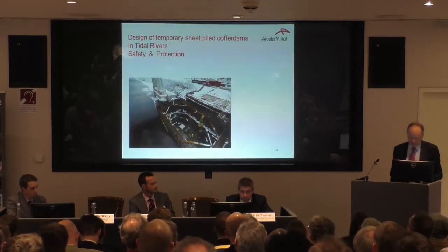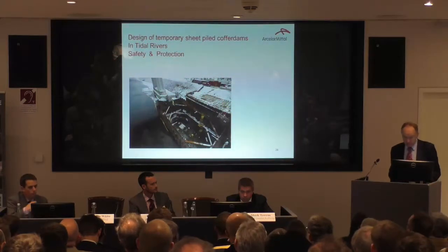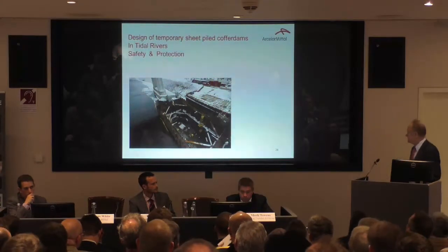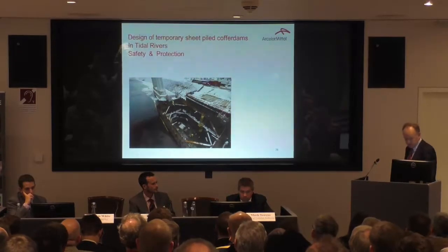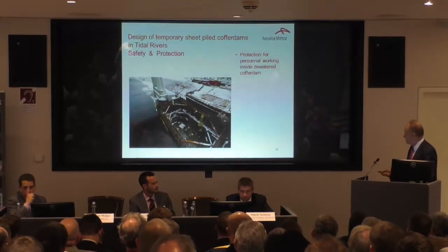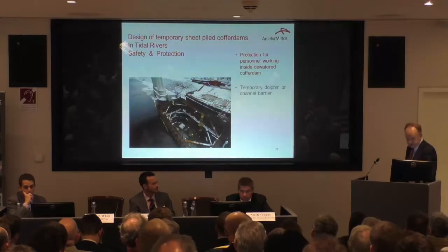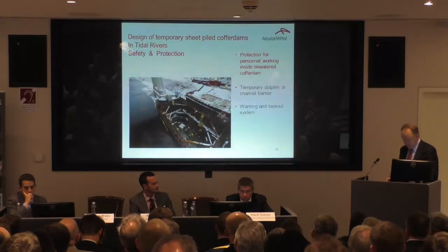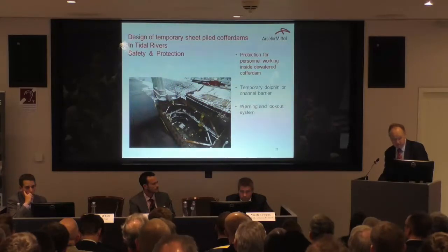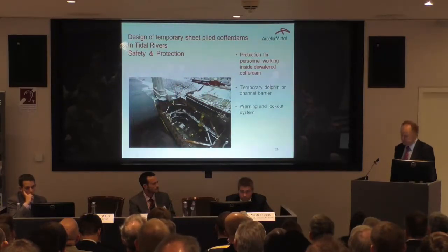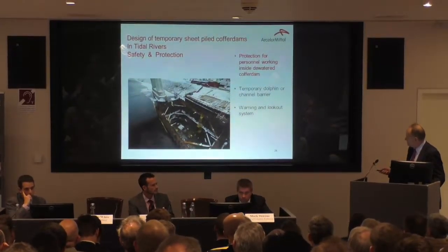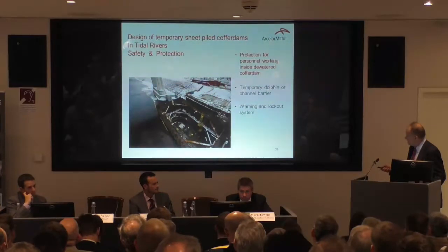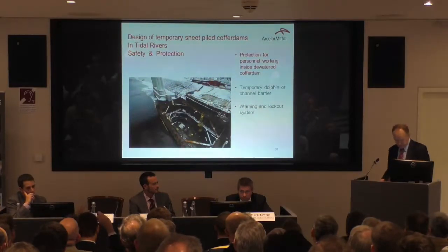Now look at the vulnerable part of the structure construction, that is cofferdams when we're dewatering. So it's quite important to protect the vulnerable face. The normal way is to have temporary dolphins or channel barriers, but the lower we get in the cofferdam and the dewater stage, there is increased risk.